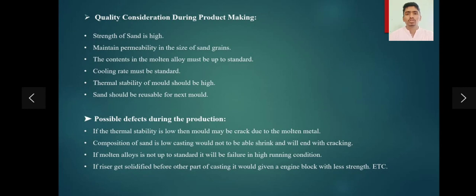If the molten alloy is not up to standard, it will fail in high running conditions. If the riser gets solidified before other parts of the casting, it would give an engine block with less strength, etc.